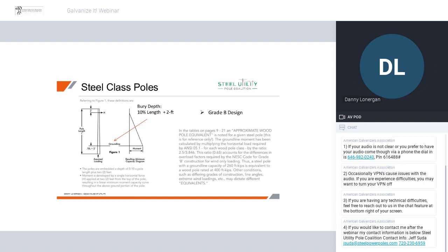If you look at wood, ANSI O5.1, and know its tip load, because O5.1 defines that, then you bounce that off the NESC by two scenarios: material and then grade of construction. From a grade B construction, which is the basis of transmission, the old method of reduction was wood times 0.625, wood meaning tip load, wood times 0.625. That was probably five to six codes ago. I want to say either 02, could have been even 97, but late 90s, early 2000s.